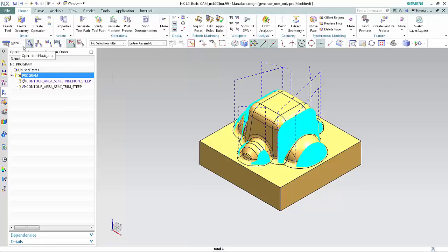By default, the data necessary to perform Smart Regeneration for each operation is retained only for the current login session. Once you log off, the data is lost and must be again created for each operation. You may, however, specify a customer default that saves this data with the part file. Although this increases the size of the part file, it allows you to continue performing Smart Regeneration in subsequent sessions.